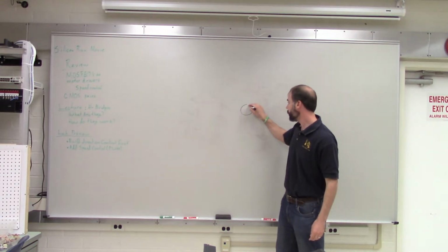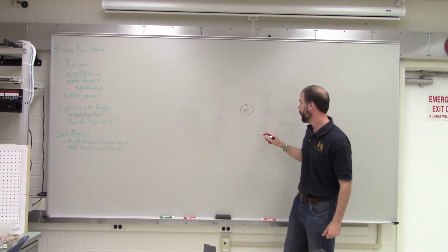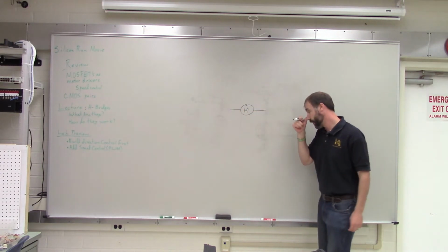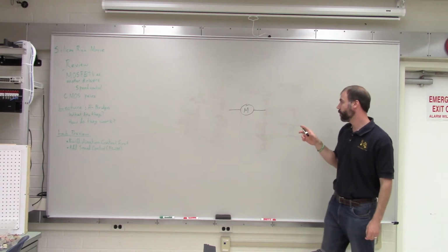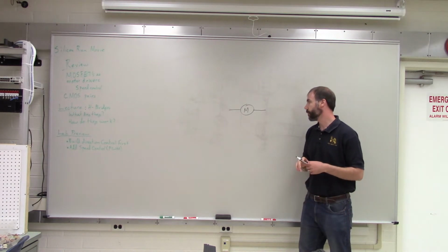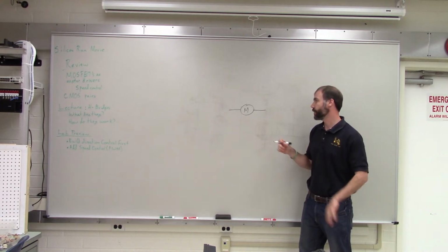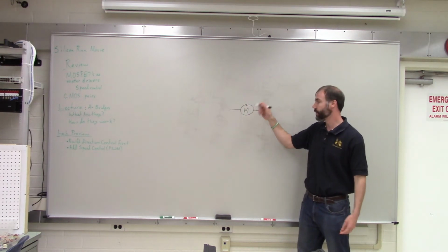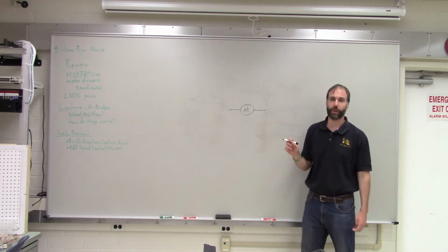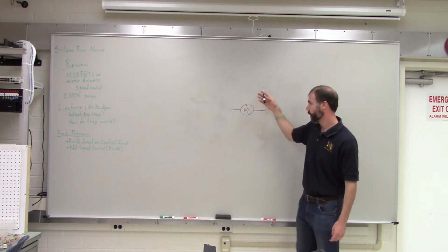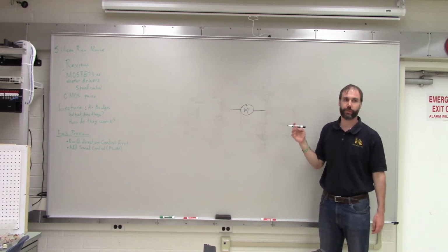So the basic idea is that you've got a motor here that you want to control, and you're going to use MOSFETs or other transistors to do this. Now, transistors act primarily like switches, so I'm going to actually draw them as switches on the board just because it's easier for me to draw, first of all, and also I think it's easier to see the idea of what's going on if I draw it that way. Okay? So when I draw the switches, just translate that into transistors, right?